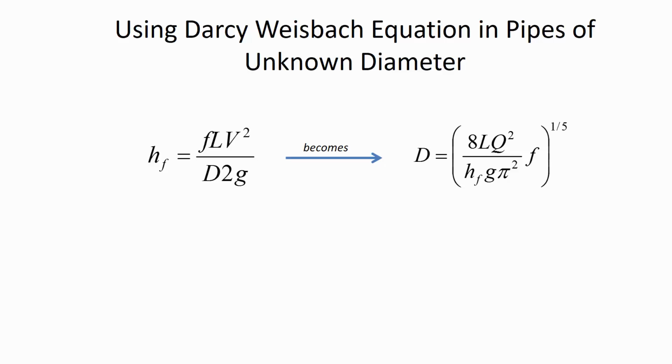And we'll substitute in the formula for pipe area. So it's f L Q squared over D 2g. And now here's our area, pi D squared divided by 4. And we're squaring that whole area. And now, since we have that 4 that's getting squared, we can rearrange and also move that up to the numerator. It's 16 f L Q squared over D to the 5th 2g pi squared, just by carrying through that area squared term. And then finally that is h sub f is 8 f L Q squared divided by D to the 5th g pi squared.